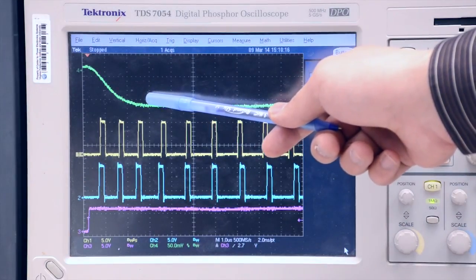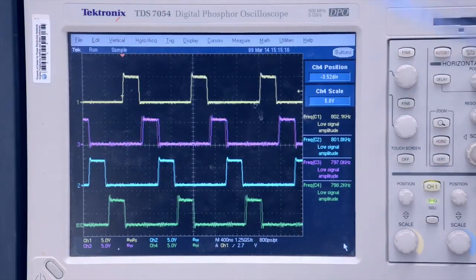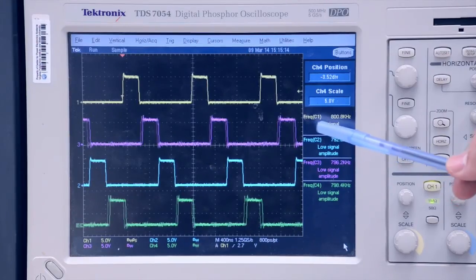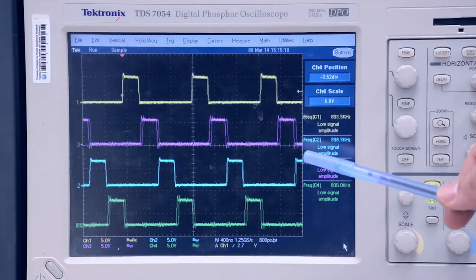Second, let's take a look at the steady state waveform at duty cycle equal to 0.25, which is the ripple cancellation point of total inductor current for 4-phase operation. You can see the PWM signal not only performs the correct interleaving angle, but also exhibits stable PWM signal without jittering.